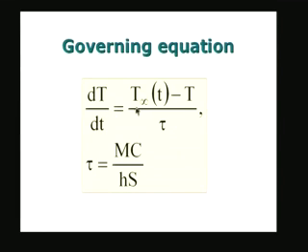So, dT by dt equals (T infinity minus T) divided by tau. This is the temperature difference, or like the voltage potential difference, and divided by the time constant, which is something like a characteristic time for the particular problem, and which is given by MC by hAs. And in the next